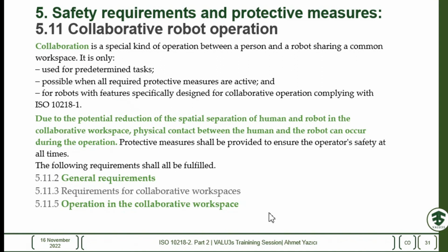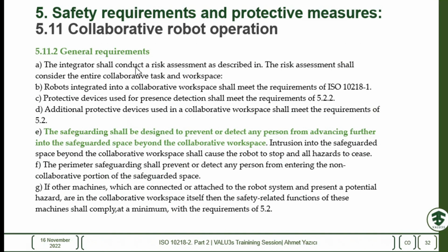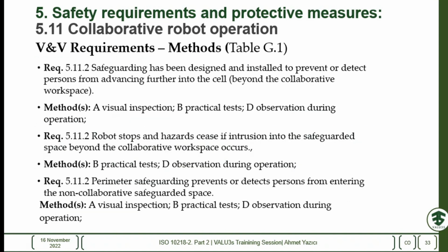For this subsection, there are some parts, but I will focus more on operation in the collaborative workspace. I will just mention these ones. These are some general requirements about safeguarding or detection. When we say safeguard, we are not just mentioning mechanical safeguarding, but also non-mechanical ones.